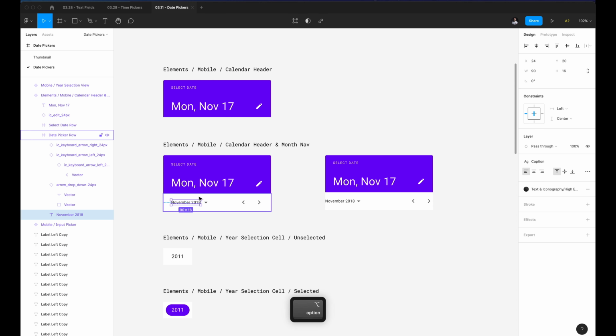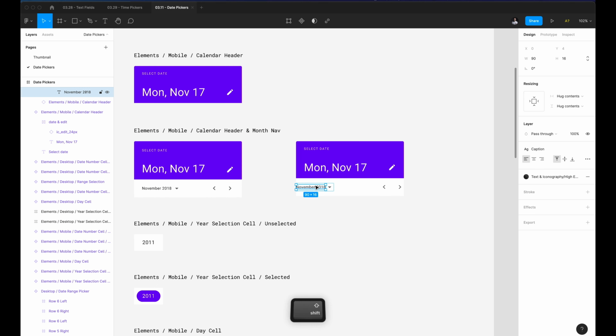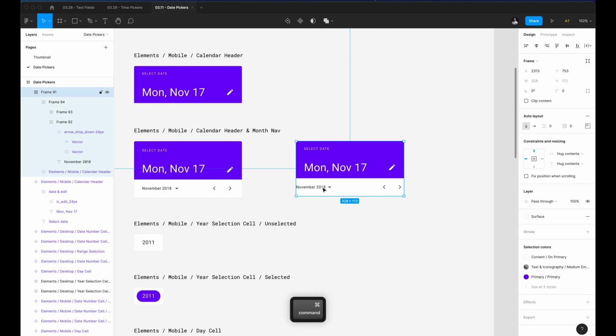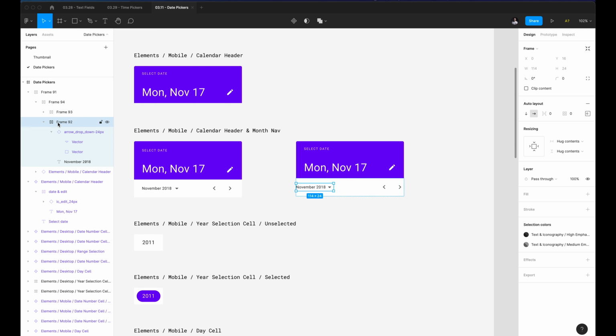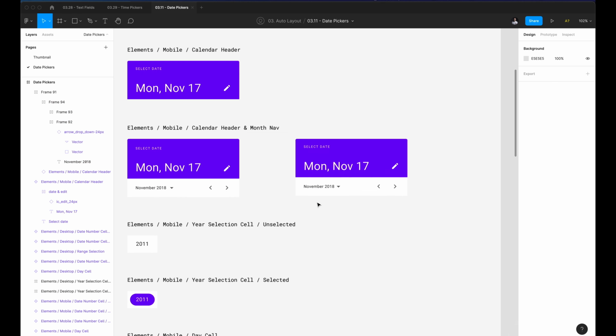And the last thing I need to do is ensure that I have the proper spacing padding here. So I could set that on the left and right. Need to reselect this auto layout layer, the parent one, and then set that to 0,24, and that pushes in the elements with the desired specs.